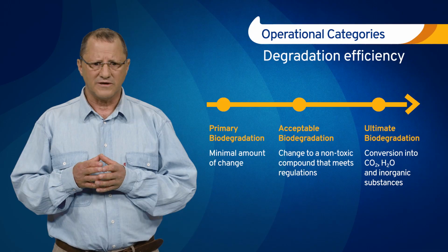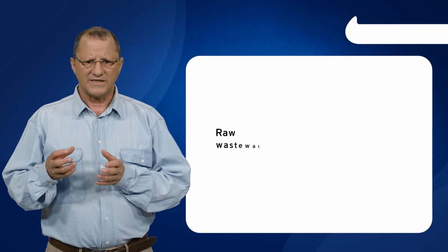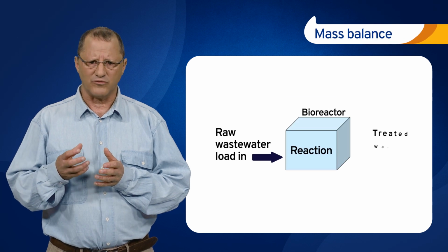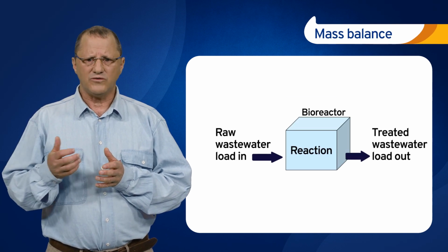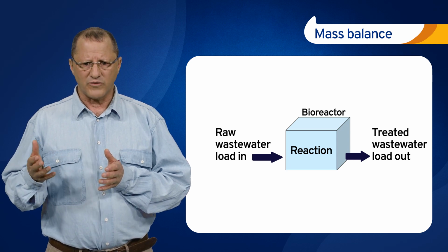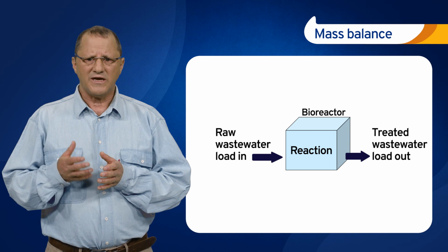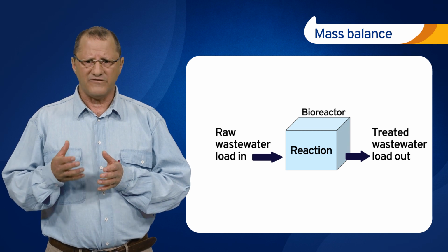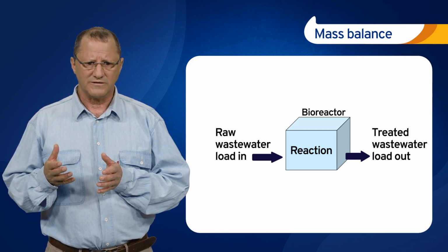Formulating the information on the reactor's input and output loads and the reaction rates into a mass balance analysis would allow one to determine the size of the reactor and to predict its performance. Lastly, taking a mass balance approach will allow day-to-day operation of the treatment process, monitoring of the operational efficiency, and making calculations for the design and development of the treatment process.